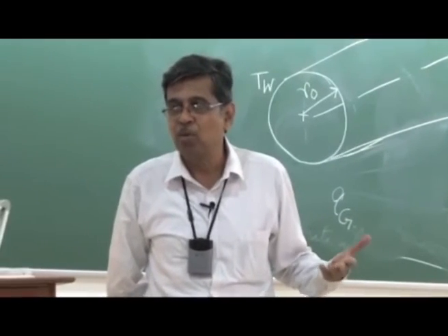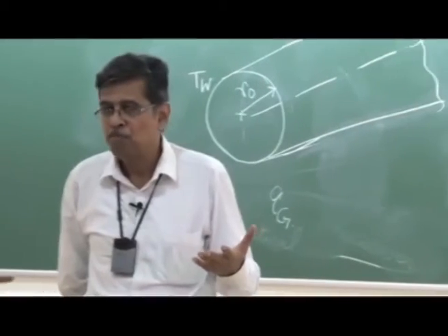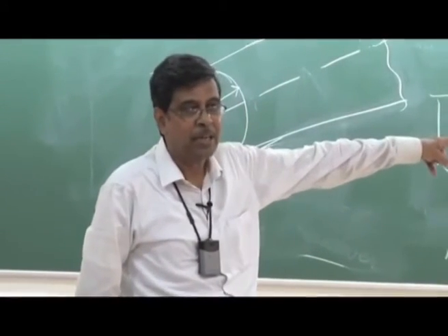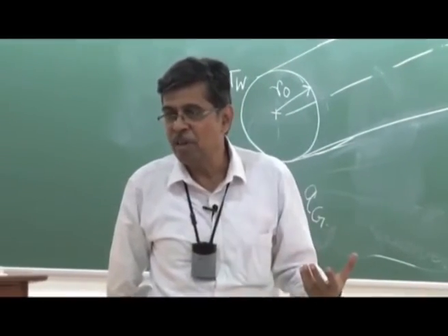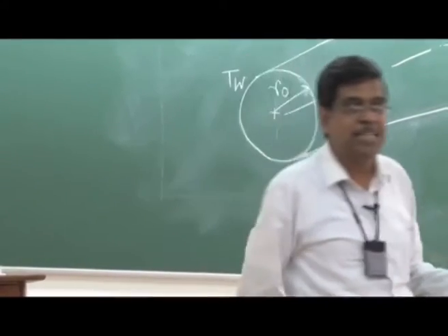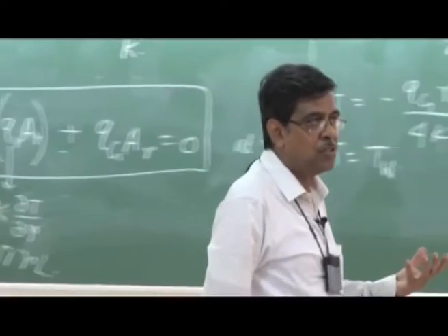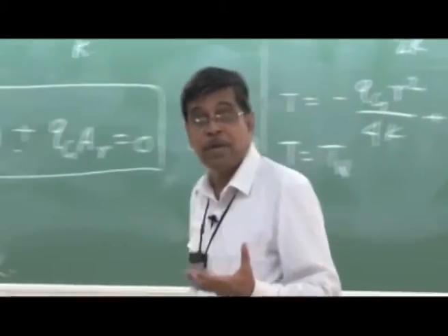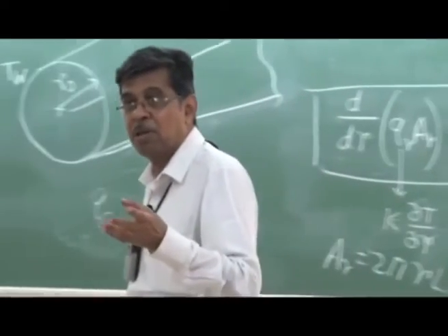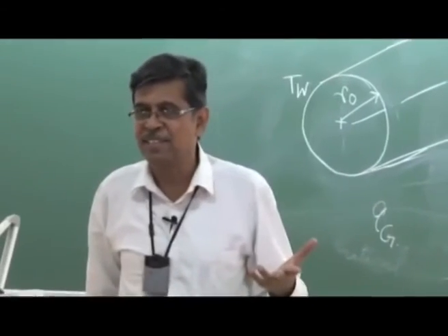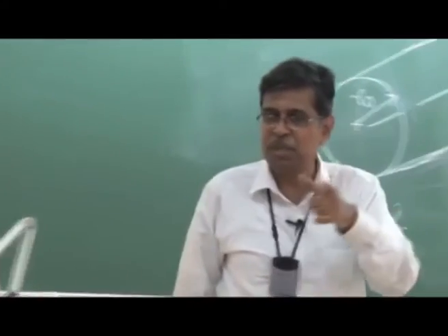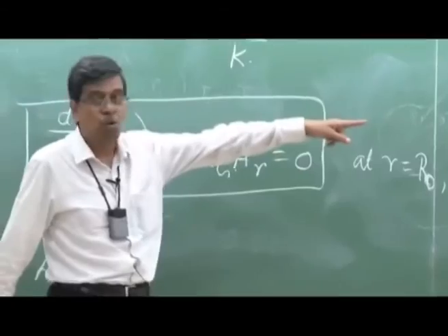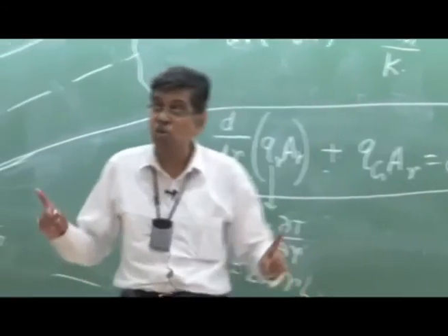Now, how do you get the two constants? Quick. What is C1, just without any boundary condition? C1 is 0, because ln R will give a discontinuity at the center. The problem is not physically discontinuous at the center, so it cannot define the function, so C1 has to be 0. But a mathematician will not leave you. Engineers are very smart, they tell many things. Okay, I understand, but it matches correctly. A mathematician will tell, no, you write a boundary condition. Your mathematics teacher will tell that you write a second order differential equation, two constants, two boundary conditions.